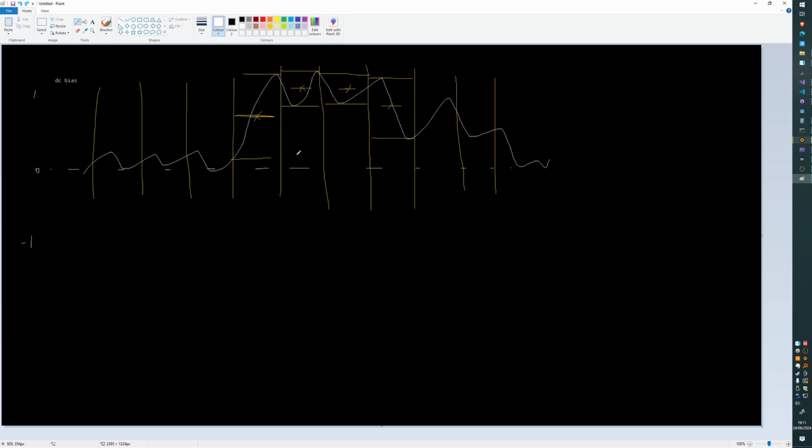So instead of doing that, we calculate a value for each frame in the entire sample by interpolating between these midpoints like this. So we'd end up with something like that. And then for each individual sample, we use this value, we just subtract that value to get the signal back down to the center point.